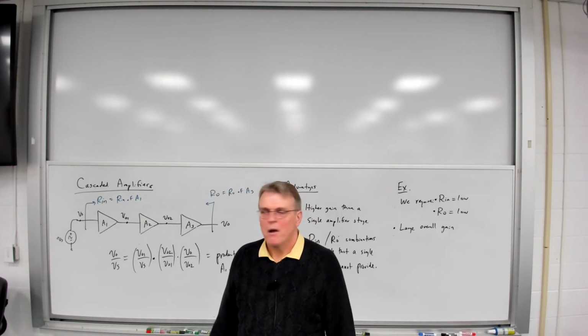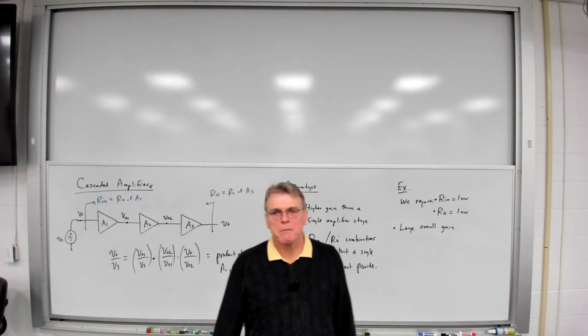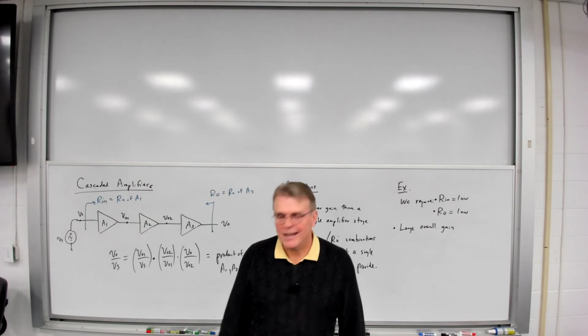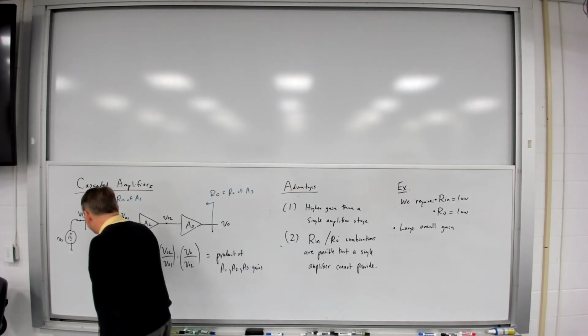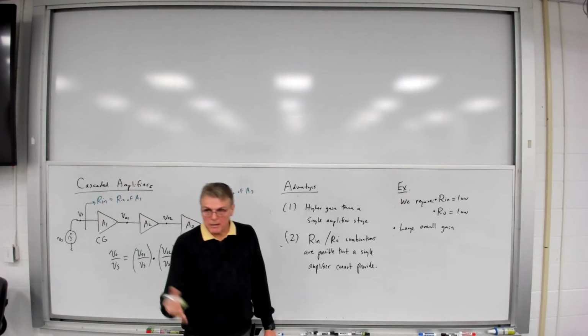Okay? What would give us a low input resistance? What single stage MOSFET amplifier has a low input resistance, relatively speaking? Common gate, yeah. Common gate has a low input resistance. High gain, but low input resistance.